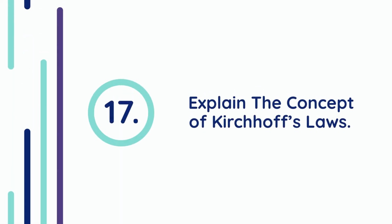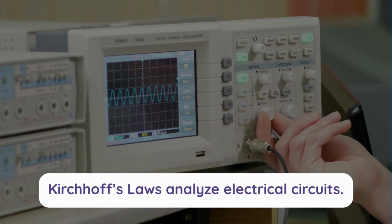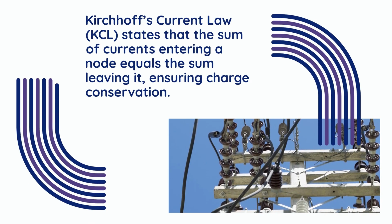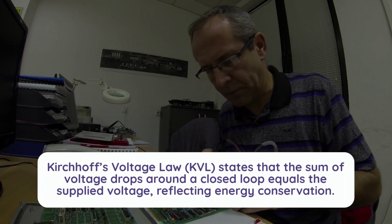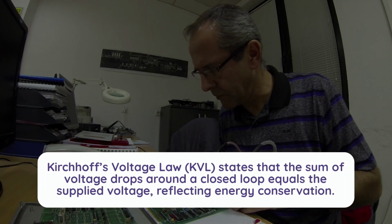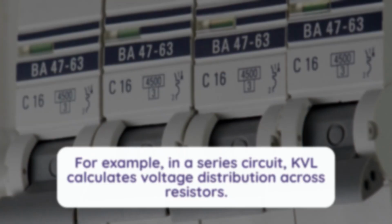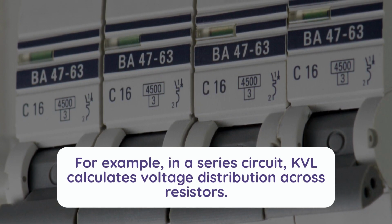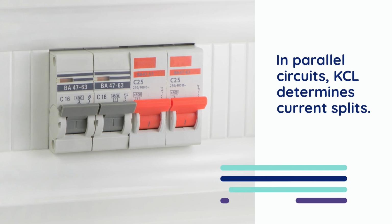17. Explain the concept of Kirchhoff's laws. Kirchhoff's laws analyze electrical circuits. Kirchhoff's current law, KCL, states that the sum of currents entering a node equals the sum leaving it, ensuring charge conservation. Kirchhoff's voltage law, KVL, states that the sum of voltage drops around a closed loop equals the supplied voltage, reflecting energy conservation. For example, in a series circuit, KVL calculates voltage distribution across resistors. In parallel circuits, KCL determines current splits.